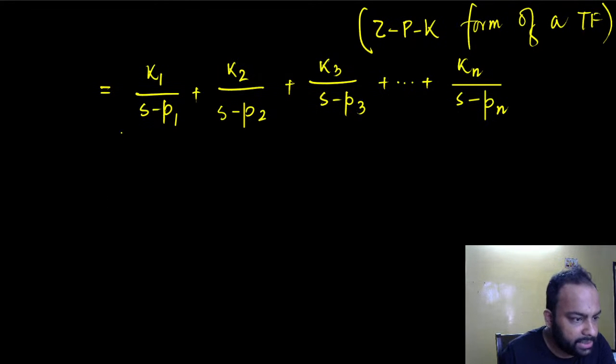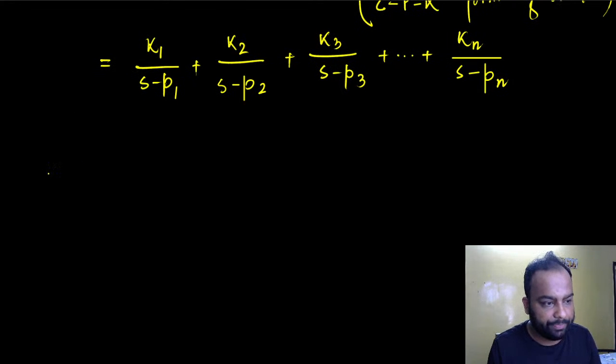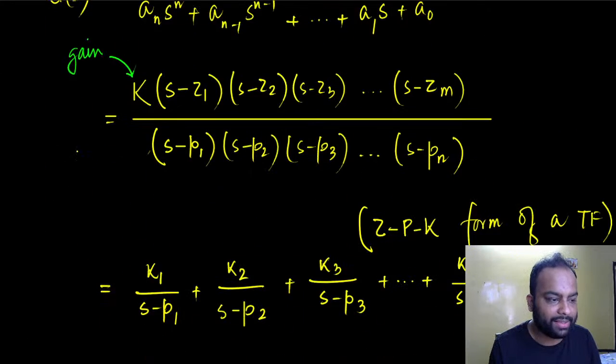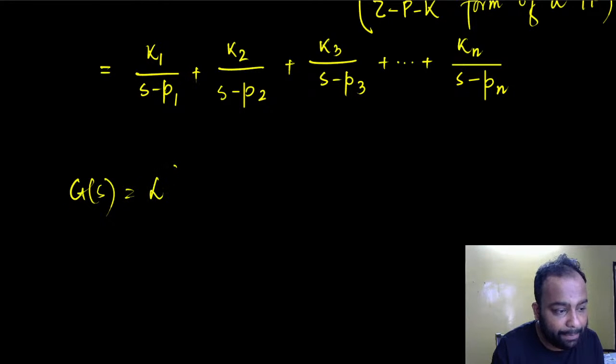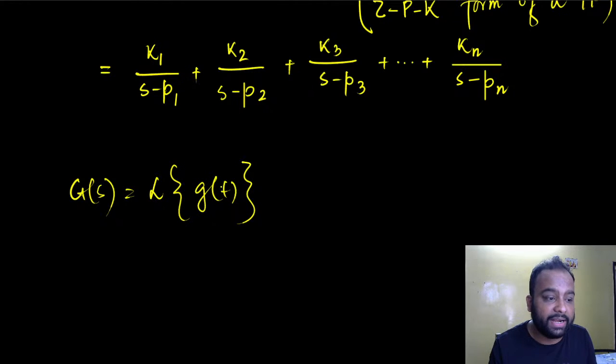All right, I think this is fine, right? Perfectly fine. So this can be done this way. But what has this been? This is the transfer function. Now what is the transfer function? We know that the transfer function is nothing but the Laplace transform of the impulse response. And for the sake of stability, the impulse response will have to be a bounded signal such that its integral is bounded, right? So we want the absolute integral of g(t) to be bounded.